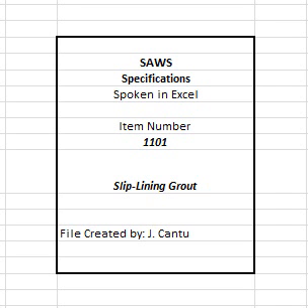2. Performance requirements: the contractor shall submit the proposed grout mixes, methods, plans and criteria of the grouting operations. The grouting system shall have sufficient gauges, monitoring devices, and tests to determine the effectiveness of the grouting operation and to ensure compliance with the liner pipe specifications and design parameters.